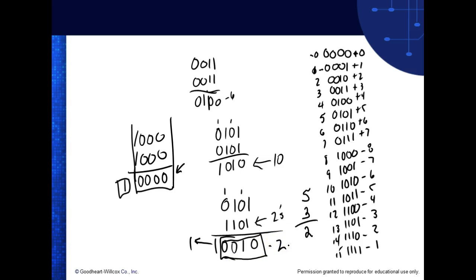So what the processor does, the processor itself cannot subtract. So it subtracts by addition. If you tell it to subtract, it takes the regular number, takes the 2's complement of the subtrahend, and adds it. So what I can do is subtract without having subtraction, by taking the 2's complement.